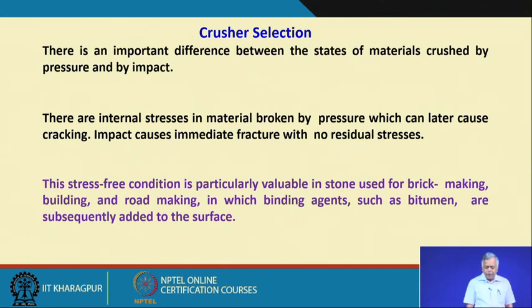So, what will happen when we are trying to break the particles based on pressure energy? As we have already said, but let me repeat it, there are internal stresses in material broken by pressure which can later cause cracking. That means when you are applying pressure, the internal stresses are not immediately released.